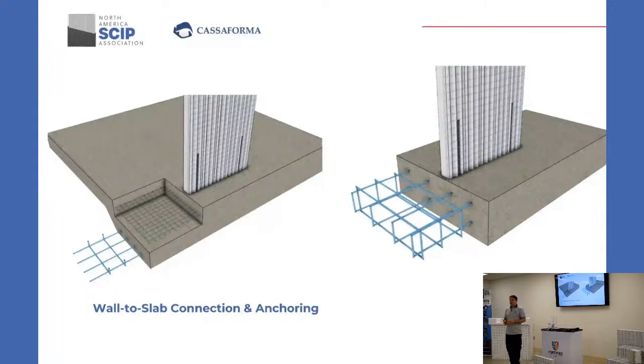Right now, for instance, we have some cases where we are using fiberglass piles. There are a number of possibilities that can be done. The only thing that you have to know is that you always have to have a rebar that connects the foundation with the panel.